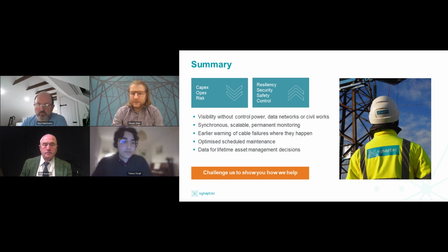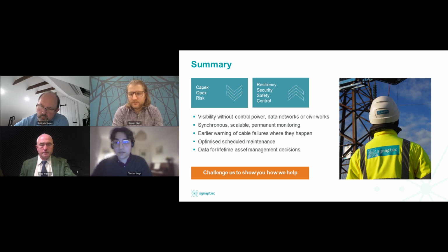Yeah, so we are able to monitor on sections of cable. So for the electrical faults that we look for, we're looking at faulted sections of cables. For defects and things like that, for the thermal side of things, we're able to get a lot more granularity. So we can look at the point temperature sensors on each of the terminations. Those are very tiny, a few centimeters in size. So we get a spot measurement there. When we combine with DTS, distributed temperature sensing, we can typically get resolutions down to 1 or 2 meters, or up to several meters if you have a very long range system.